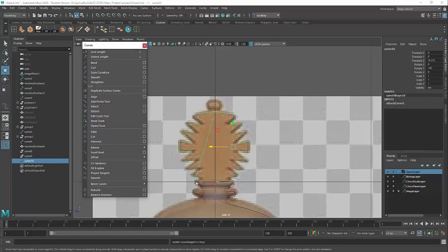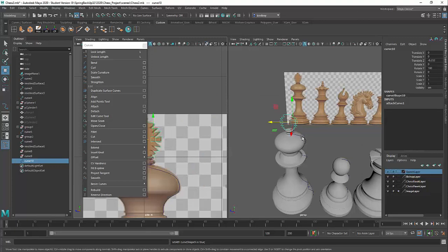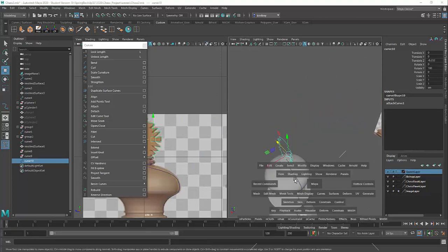And you'll see what happened is some weird little line has jumped around. The reason why that's happened is because we duplicated this and flipped it over to here. So I undid that by hitting Control Z. So what we have to do is reverse the direction of this curve here. Think of it like reverse normals, and it's down here at the very bottom. So once I click on that, then it's okay. And now I can hold the shift key, click on this curve, and now click attach, and look at that. Now we have a complete path that is enclosed, which is really cool.